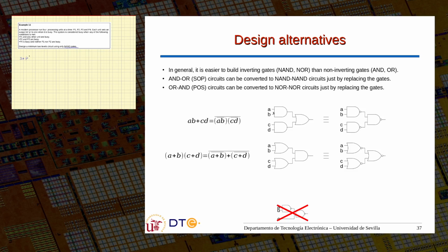So once I have designed a circuit or have calculated the sum of products, I can decide to use AND and OR gates or simply NAND gates for everything. We don't have to transform every single gate. Just take the whole expression, sum of products, forget they are AND and OR, and use just NAND gates.